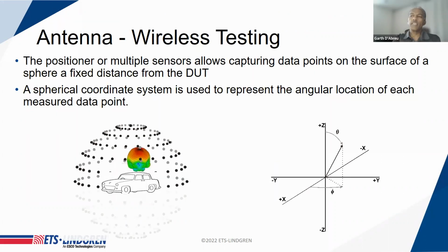On the antenna side, it's fairly well defined. There are a number of techniques that are available for performing antenna measurements on antennas that have different propagation characteristics. The full spherical measurement is something that's used for very low gain antennas. If it's an antenna that's ground-based, you can do far field measurements at very great distances. If it's an antenna that's very high gain, you can do a full spherical measurement or a planar scan or a cylindrical scan. All of these techniques have been in the industry for decades and are very well understood.